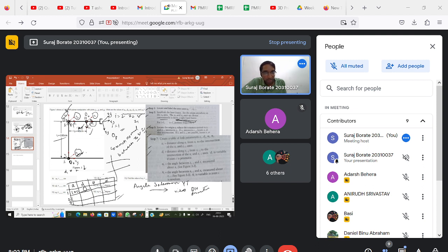And intuitively, if you think, there is no offset between these two. You remember the example of offset. The links are not out of plane. They are in the same plane. When we say out of plane, it is along the z direction they should be out. If there is a joint and the angle is moving, it should be above here and it should move. That is not happening. So it makes sense, d is 0, and intuitively also you can check your answer is right.